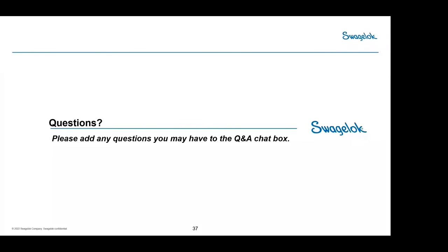Good question. Thank you. I highlighted only a couple of things here, but there are several factors, and we have technical people on the call who understand this. When you look at the system-related factors, you have to look at the lines in and out on the system side, not only the valves, tubing or fittings. So when you look at the fluid system as a whole, you need to understand how the flows are, where the pressure drops are, and where your lines are coming into the valve and how they are responding.